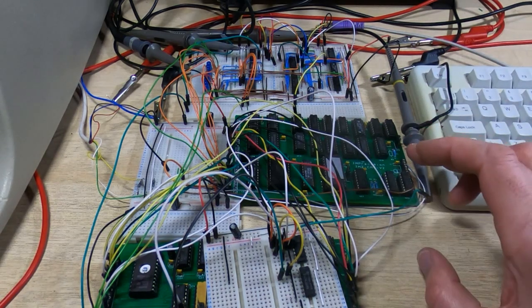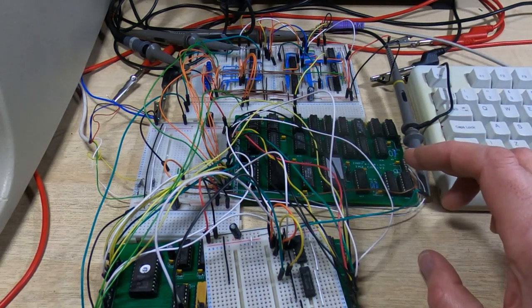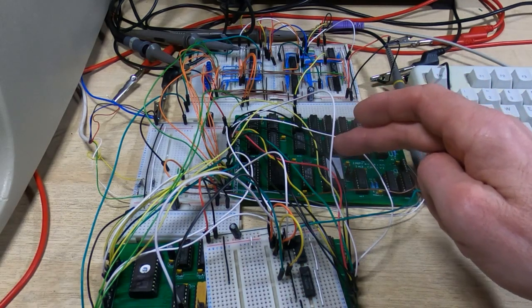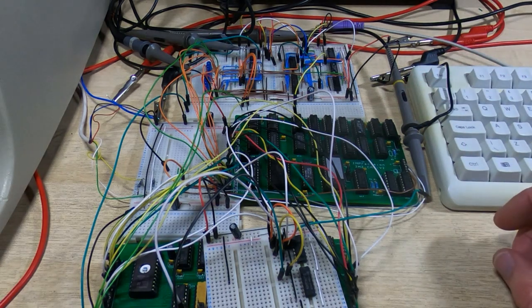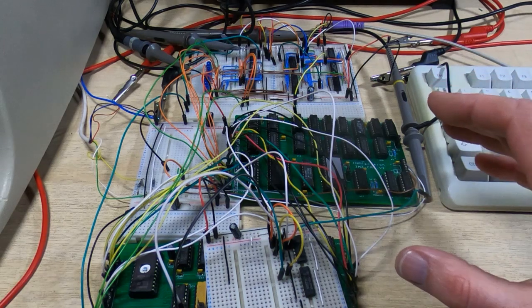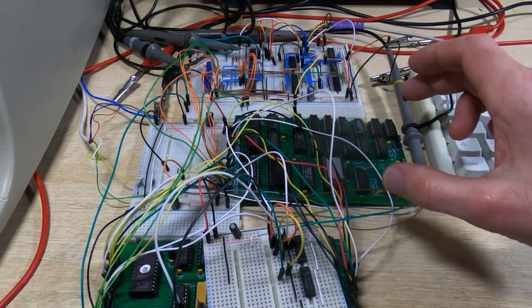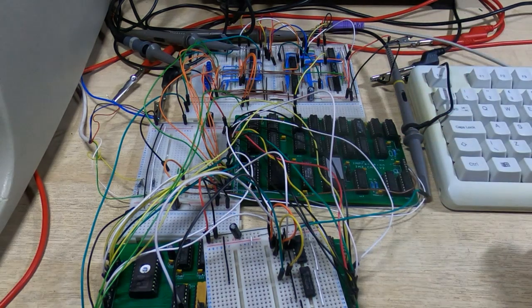In our case, you may recall from an earlier video that I decided to use a spare bit on the SRAM data to store the cursor information. So when that bit is set, we use that particular character as the cursor generation. So it's a small piece of additional circuitry to allow us to do that.